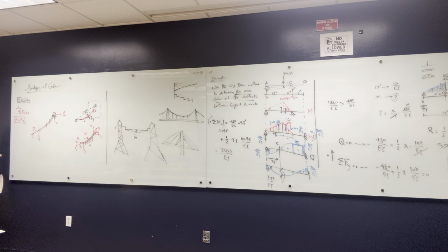All right. What if I wanna find out the vertical component, or I wanna find the tension in this cable? How can I find it? If you know the angle here, theta, you can find the tension. Why? Because I know that T1 is equal to, let's say, H1. Both are right. If you want to find H1, the horizontal component is going to be equal to T1 cosine theta, right?